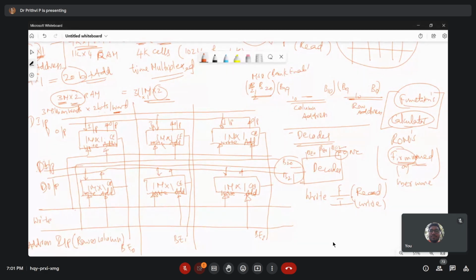But for userware, or customer end programmed elements, you can use them for generating your own logic. That means you can program this. How many times you can program depends on the type of ROM you are using, and they are classified into PROM, EPROM, or EEPROM.